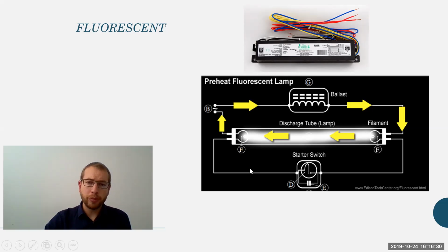Because we want to be regulating this electric discharge at all times, you need a way to manage that off of an alternating current. And that's where a ballast comes in. I've got a photo up here at the top of a ballast. Sometimes if you hear a buzzing or the lights flickering, people will say that's a bad ballast.